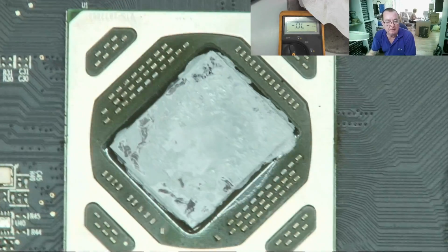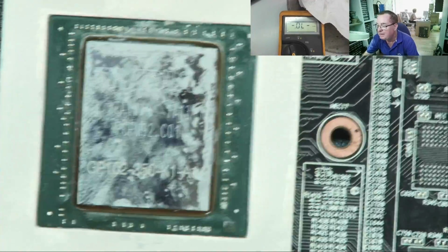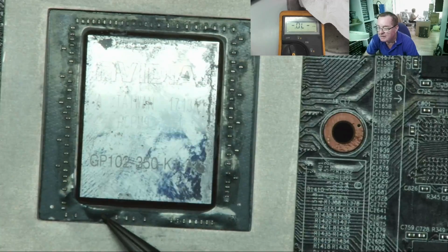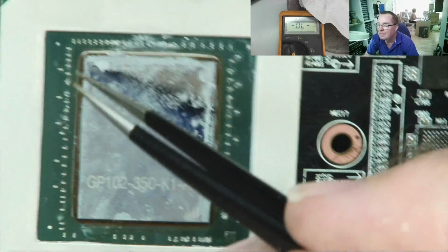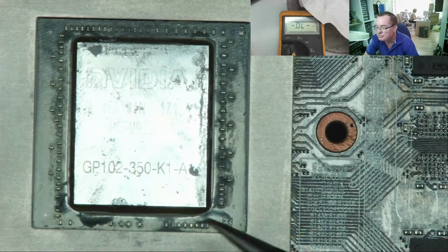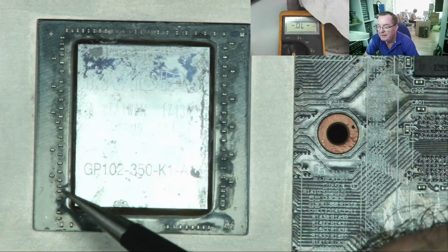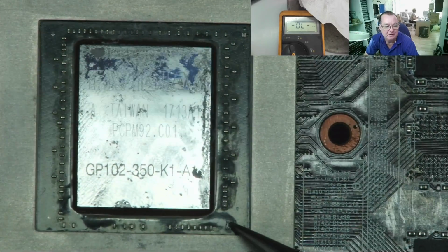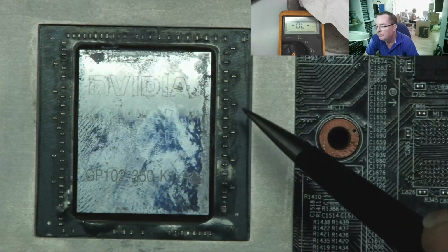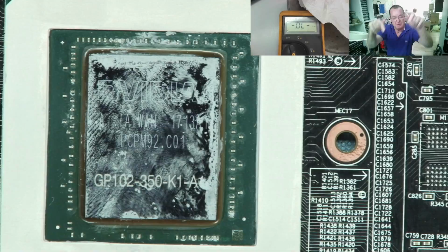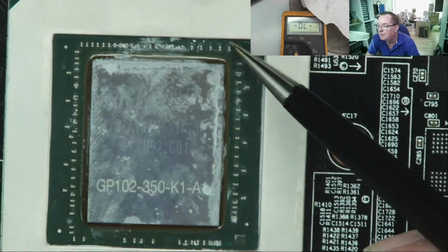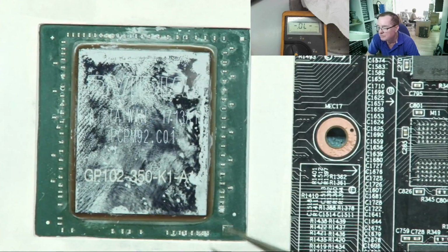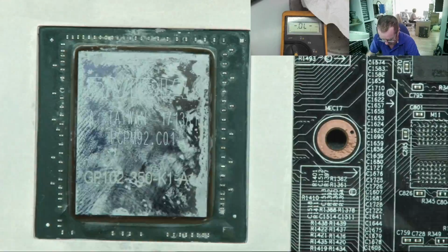Okay. If you'd like to see one that has been damaged by hot air and an attempted repair, here is one. Can you see what I'm trying to say now about the bulged areas on the substrate? So if you see anything like this, then you have a dead GPU, and to be honest, it's been killed with a hot air gun. It's been overheated. They won't fail this way. If somebody wants to say yes, they will, comments below, but in my experience, anything like this is actual damage by a botched repair attempt. Okay, so that's the sort of thing to look out for.